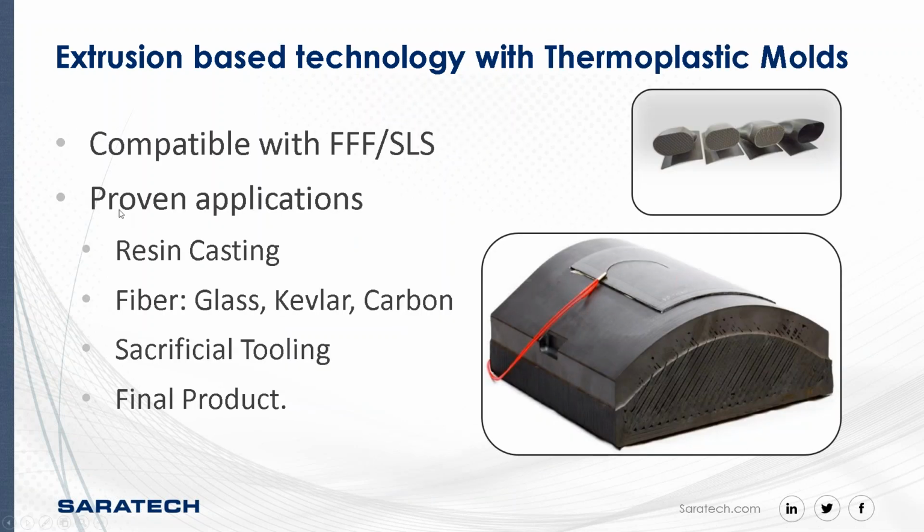So you can see the images above. For composite manufacturers, additive manufacturing can fundamentally change the procedure for creating complex, hollow composite parts. Traditional composite manufacturing techniques work well to produce basic shapes with constant cross sections. However, complex composite parts with hollow interiors present unique manufacturing challenges. Internal tooling, which I'll refer to as a core, is used to create the hollow features in a structure. Depending on the geometry, some internal tooling can be easily removed after molding. However, any configuration that traps the core inside requires sacrificial tooling.